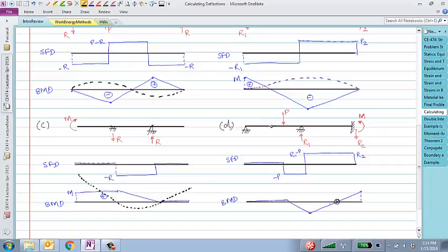How about this guy? I have this beam. How many points of inflection do I have here? One, right? On this side, the curvature is positive, smiley face. And on this side, the curvature is negative. So indeed, there is one point of inflection, which is the point where the moment changes sign from positive to negative, where the moment goes zero, which helps us draw the deflected shape.